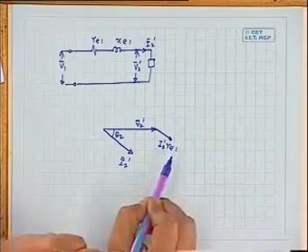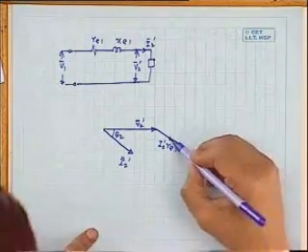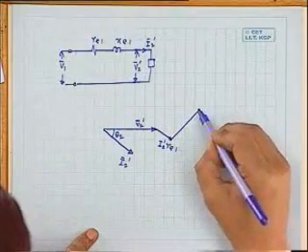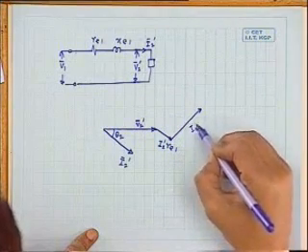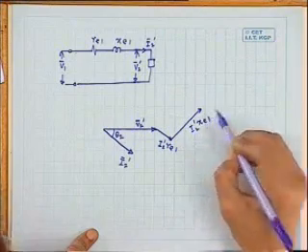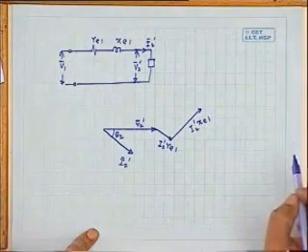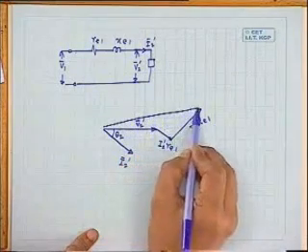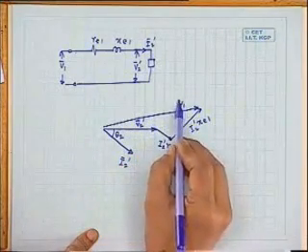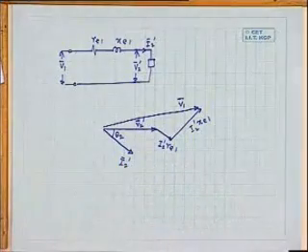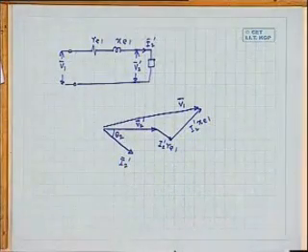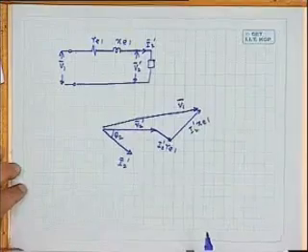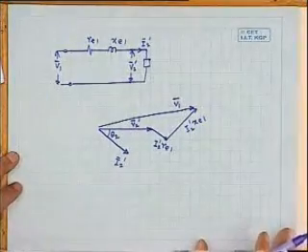This will be I2 dashed RE1, in phase with I2 dashed, and then I2 dashed XE1 will be this one, and this voltage will be, I have drawn on a larger scale so that we can understand, this V1 you will be getting.